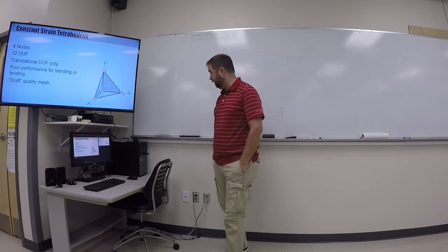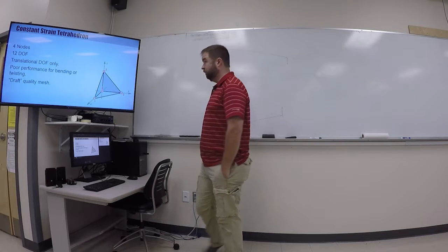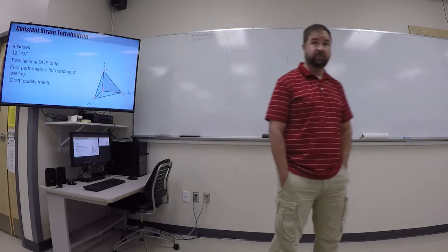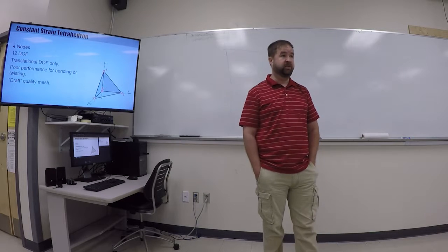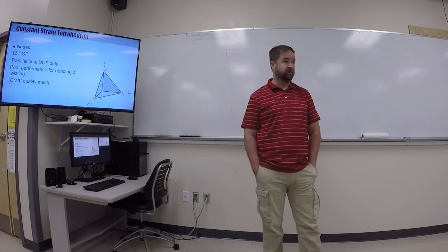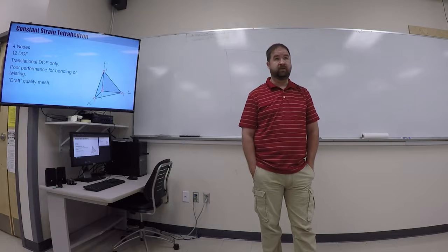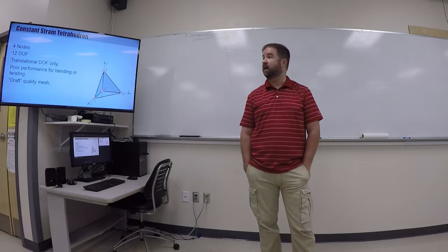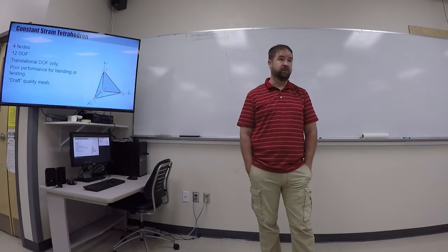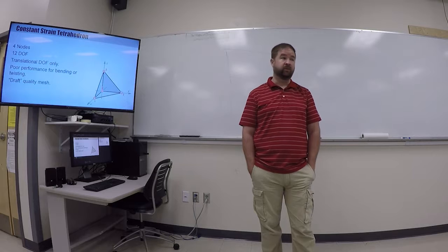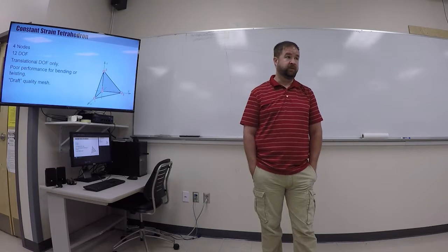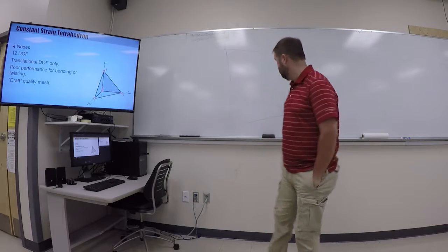So obviously, as the geometry gets more complex, we eventually have to start using three-dimensional elements. We try to avoid it because three-dimensional elements means more degrees of freedom. And more degrees of freedom means longer times to mesh it, longer times to analyze it, and then in some cases, not as good results. A lot of times on three-dimensional analyses, you're not going to get exact results, which means I need to continue to refine the mesh to get closer and closer to the correct values.